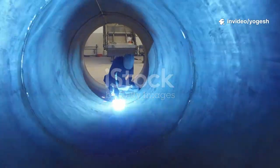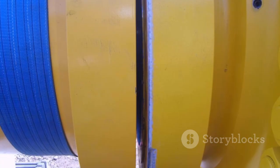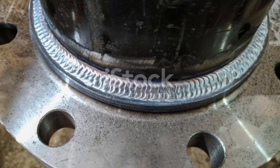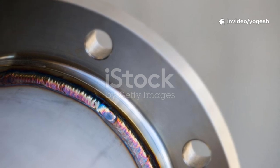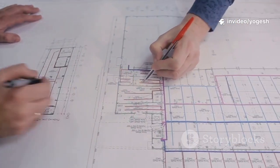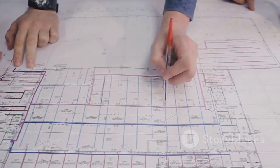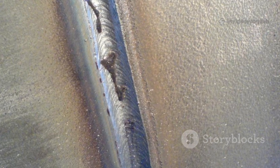Two symbols control weld extent and location: the all-around and field weld symbols. The all-around symbol, a small circle at the reference and arrow intersection, means the weld goes completely around the joint. This streamlines drawings and eliminates ambiguity, especially for round or square connections. The field weld symbol, a solid flag, indicates the weld must be made on site, not in the shop.